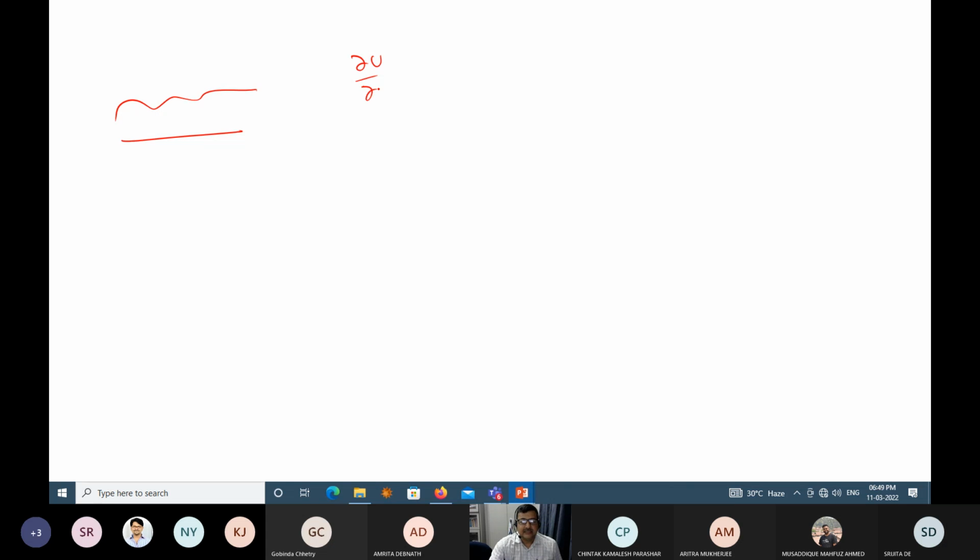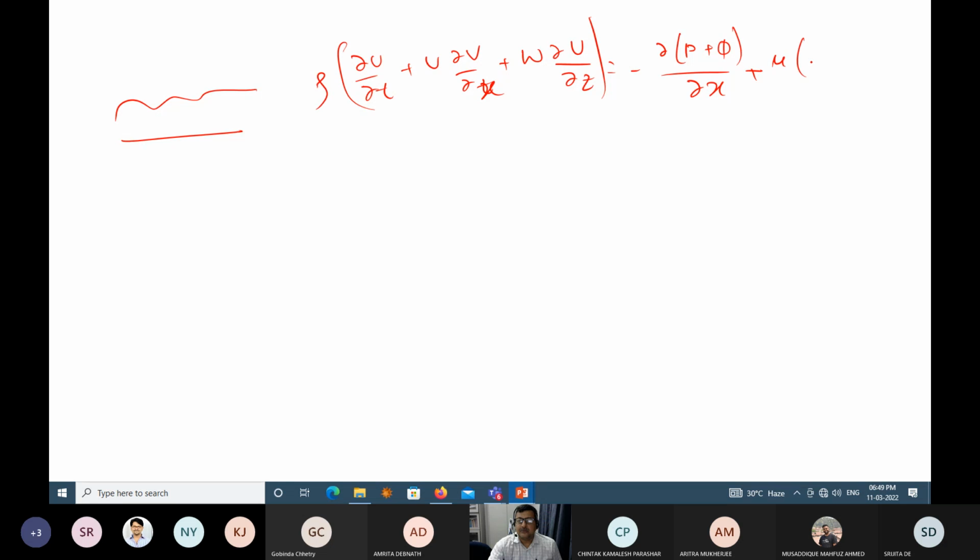Rho times del u by del t plus u del u by del x plus w del u by del z is equal to minus del of p plus phi by del x, where phi is the body force potential; I just put a rho here so that I don't get into trouble, plus mu times del square u by del x square plus del square u by del z square. This is my x momentum.